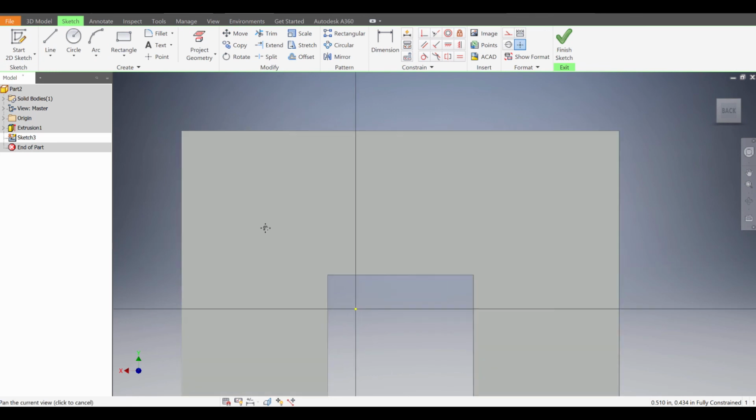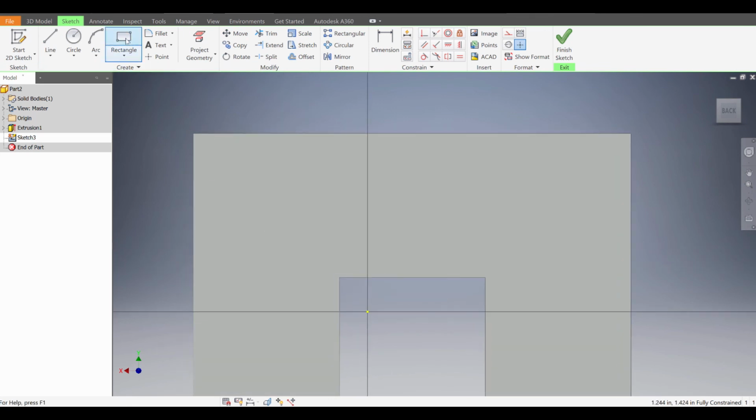And to draw out this puzzle cube piece, I'm going to use the rectangle tool. And I'm going to start at that corner. So you see how that corner went green? I'm going to click. And I'm going to drag it over to this corner over here. See how that went green? And I'm going to click. So because I know each of these are 0.75, if you did it like that, you're good. It's one puzzle cube. Otherwise, you could use the dimension tool and you could dimension each component.